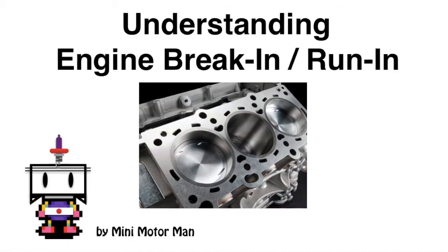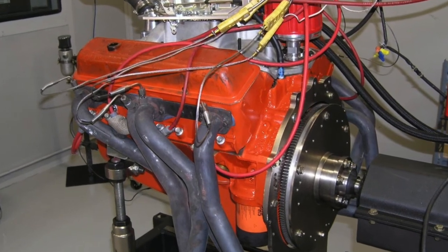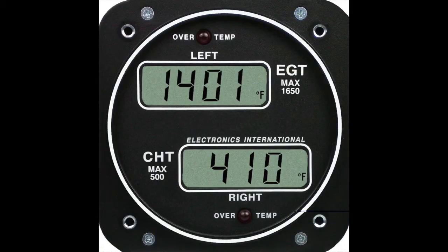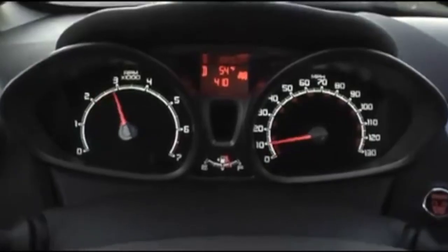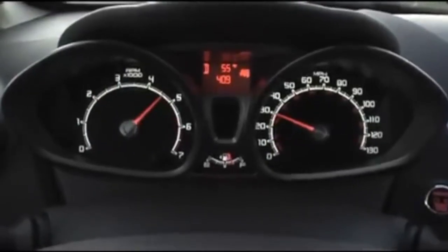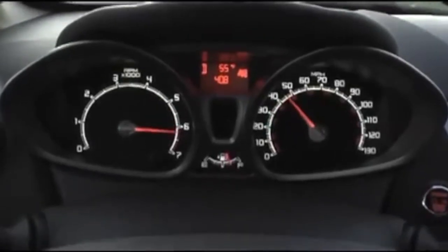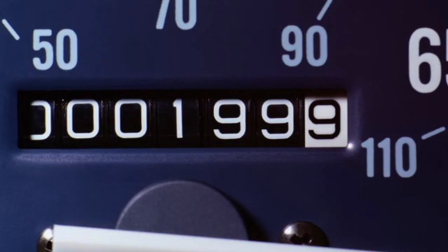Now, to an old school mechanic like myself, or old school trained, this seems a bit unreasonable and strange, but if you took time to explore and understand the technology, you would then realize why the rough braking method can indeed work without the use of a dynamometer and a vast array of gauges to monitor things like exhaust gas or cylinder head temperatures, because the newly rebuilt engine is finished almost to a level of an already broken-in engine, and therefore much less heat buildup and stress will occur during the hard run-in, and also much less time is needed to wear in the appropriate surface.